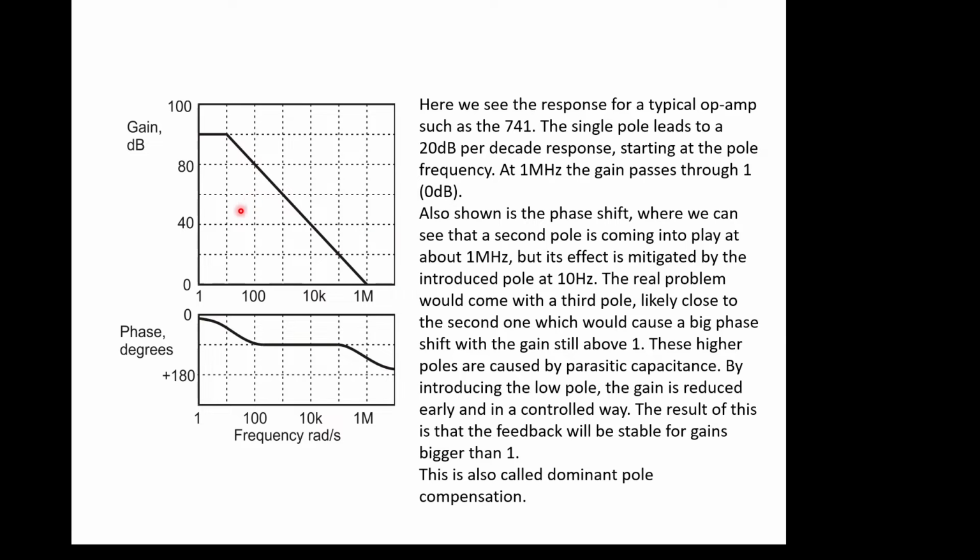And we would expect, having looked at this graph, to say that this graph should go flat across here, but the graph is actually dropping down. What that's telling us is there is another pole at 1 megahertz or shortly around it, which is causing this to go down at 40 dBs per decade. But they don't show you this in the datasheet graph. That could be an issue, because then you're starting above these frequencies, just starting to get to 180 degrees of shift, which we know is a bad thing for stability.